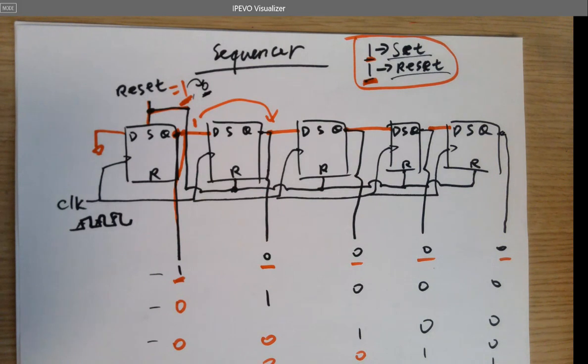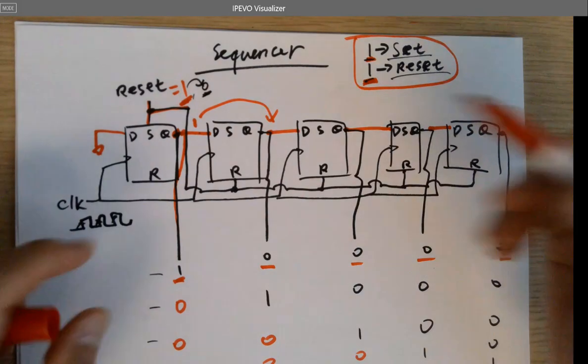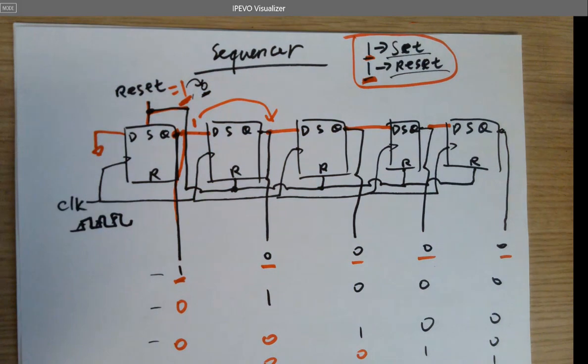Or it's writing the first one to 1 and then using the reset pin to set the other ones to 0. That's right. And then from then on, it's writing 0, which stops the other 4 from changing, and they're just getting shifted over.